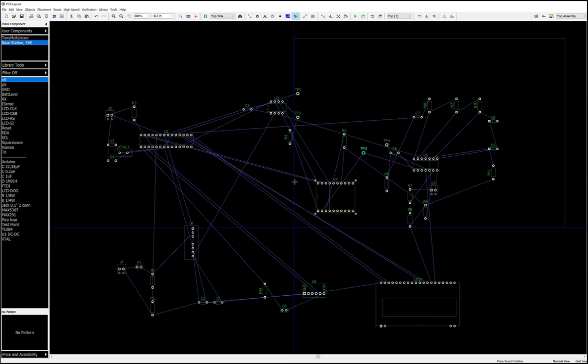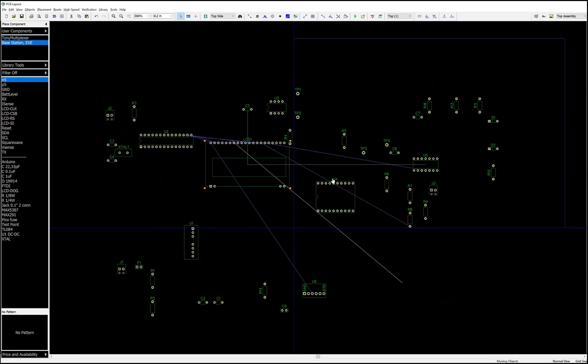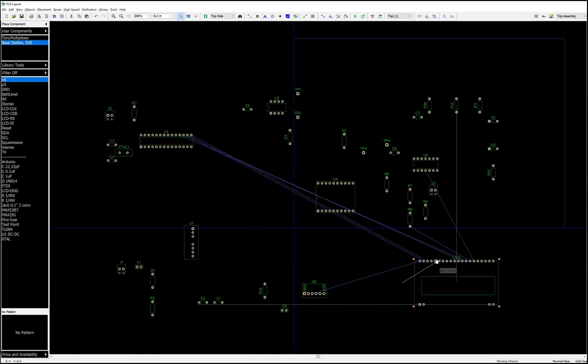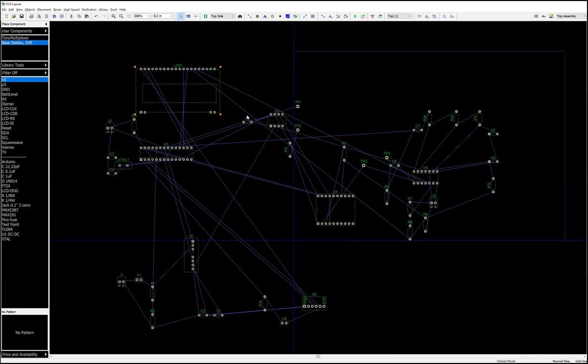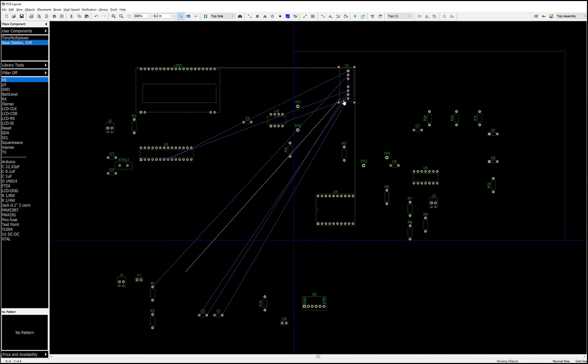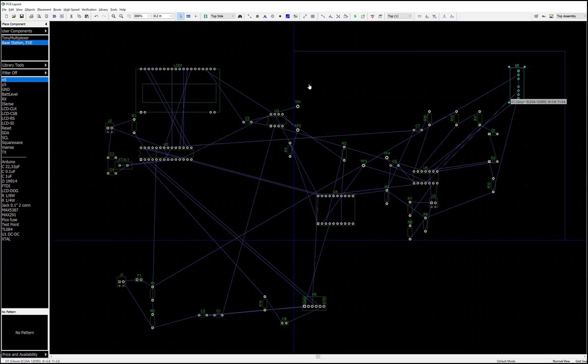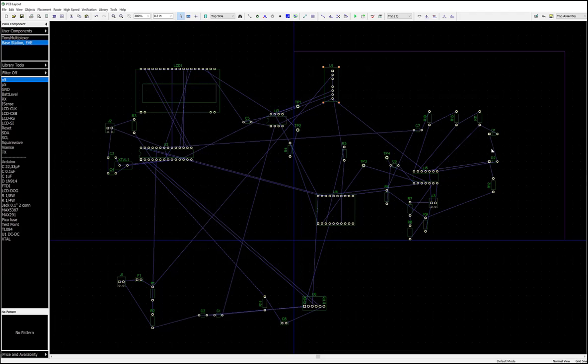Okay, so you want to go back to your schematic and start grouping like components together. You can see roughly how they're connected here, but many of these wires are sort of arbitrarily drawn. If I move this LCD screen up here, it's not necessarily even drawing these logical wires to the closest possible value. If you press F12, it'll update those wires. Did you see what just happened? If I press F12, it'll update the wires to snap to the nearest logical connections where they should be snapped. Because after all, for a ground wire, ground is all through these things.